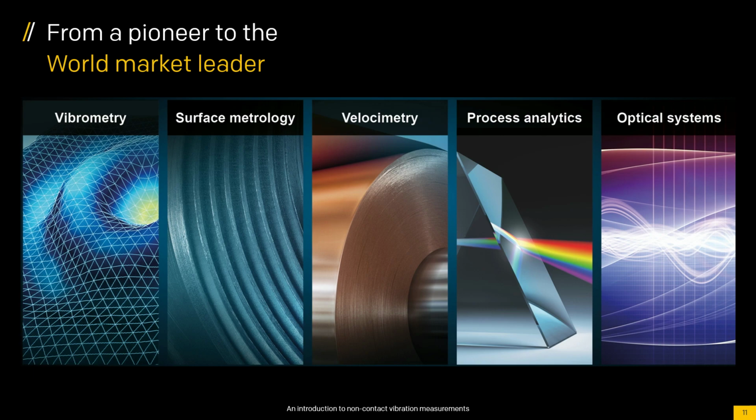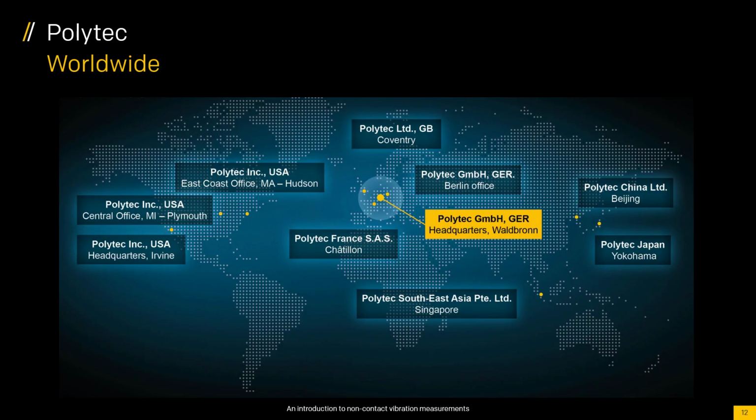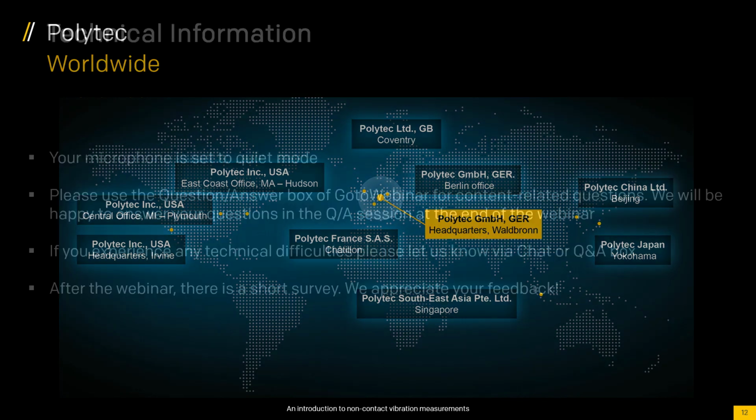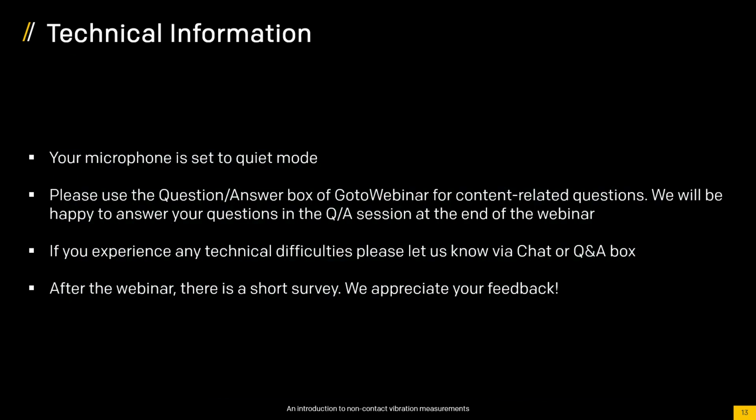I'm going to measure 100 hertz, 6 microns, whether I am a meter from the wall or 5 meters from the wall. That measurement is not going to change. It doesn't care about the absolute standoff distance. Now, take that concept to a hexagonal shaft. If it's not cylindrical, that distance is changing, but a vibrometer really doesn't care.